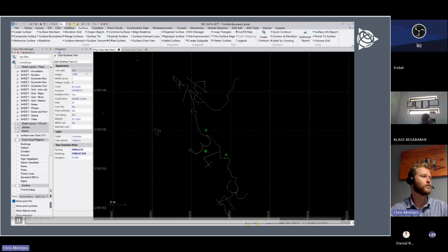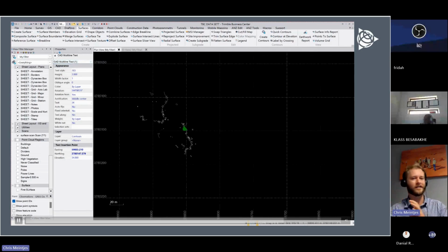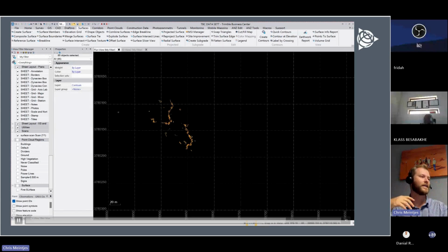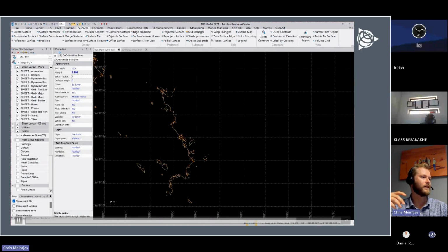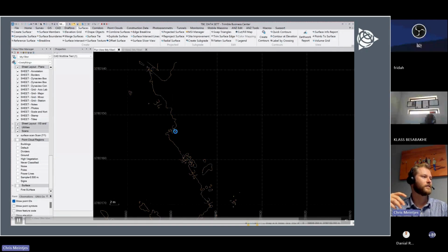You can see I'm showing you how you can move them. Obviously, this is all stuff you can specify before you generate your contours, how they sit, which label only the ends, label along. So I've selected all of it, and I'm just going to select a global height and width factor of our text. So there we've got contours.